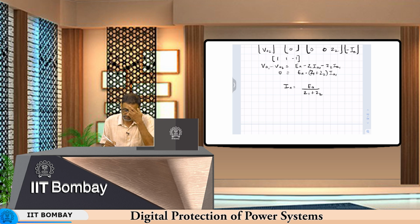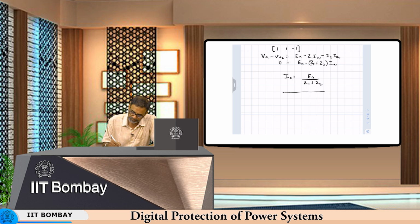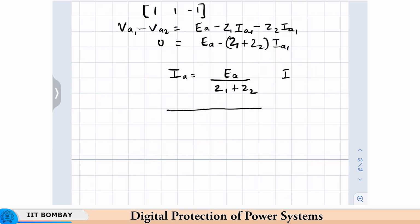Okay. What does this suggest? In the last type of fault, we got a series connection. Since IA1 equal to minus IA2, or IA2 equal to minus IA1, this suggests a parallel connection.